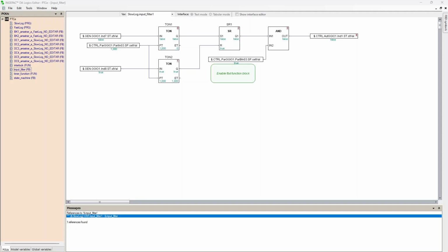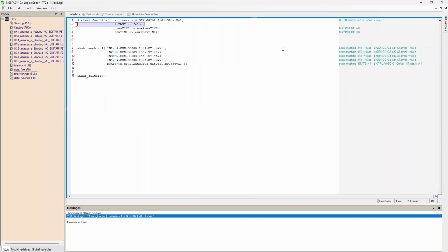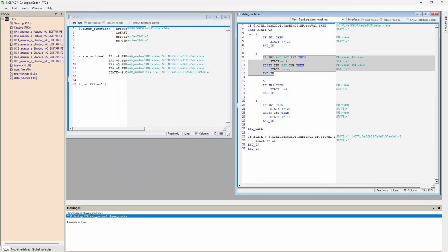Additionally, the value given to the integer parameter is used to set the on-delay timer's activation setpoint. On the contrary, the timer function implemented on a ST-type function POU does not update since its parameter is disabled. The last function and ST function block is also disabled by the fourth Boolean parameter.